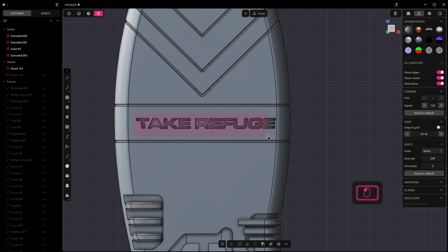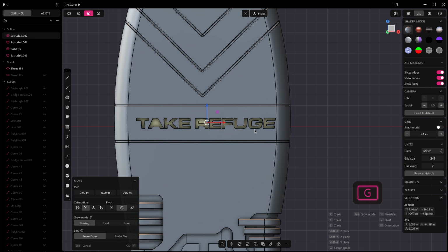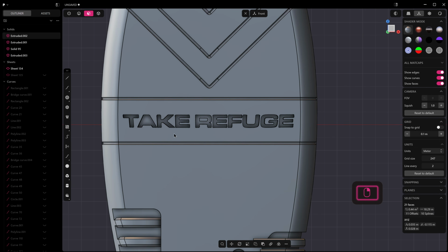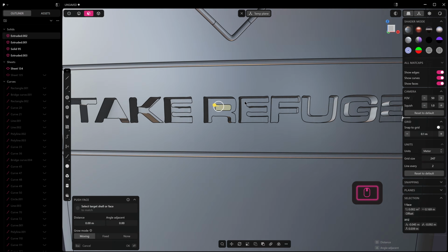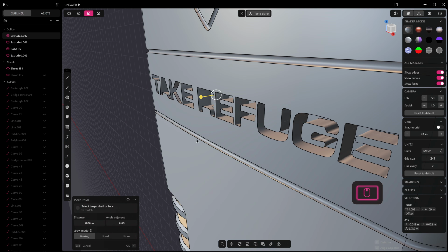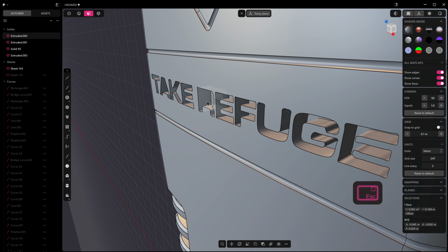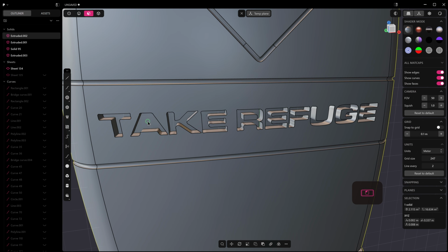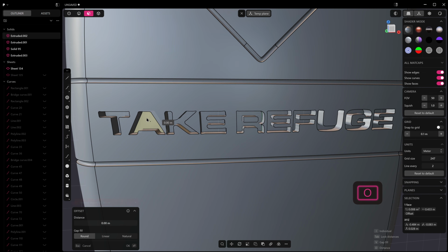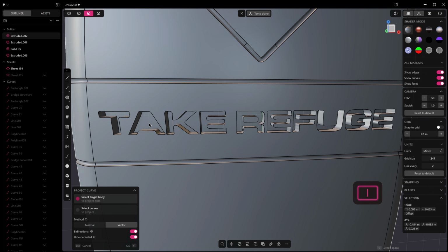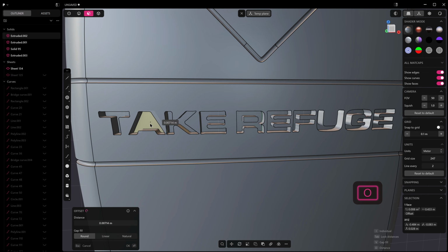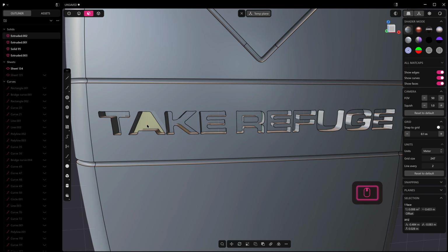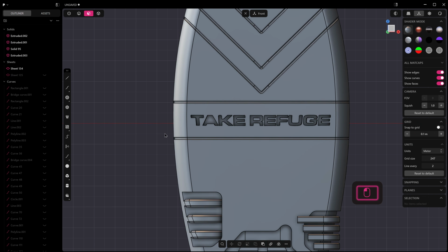And we can try and move these across actually. So if we go into face mode and select them all, we should be able to just G and pull them across. It might not like it, but we can. Okay, and you might notice that we got some of the backs of the curves pulled out like that. So we can hit extrude and pull that out. And with the A, something similar has gone on, so we can O to offset if it'll allow us. Or we could just put a triangle in there, or not even worry about it.